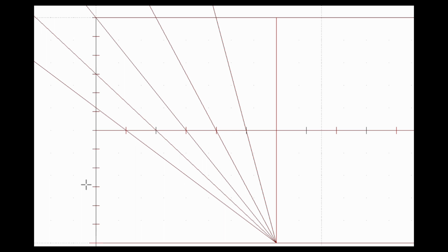So these are the lines that we have got. Now, similarly, we have to connect this point with the points that we have on the side of the rectangle, which will give us the intersecting points in the first quadrant, and then we'll be able to draw the curve. So let's connect this point with these points. I'm using a different color so that we'll be able to distinguish the lines separately.